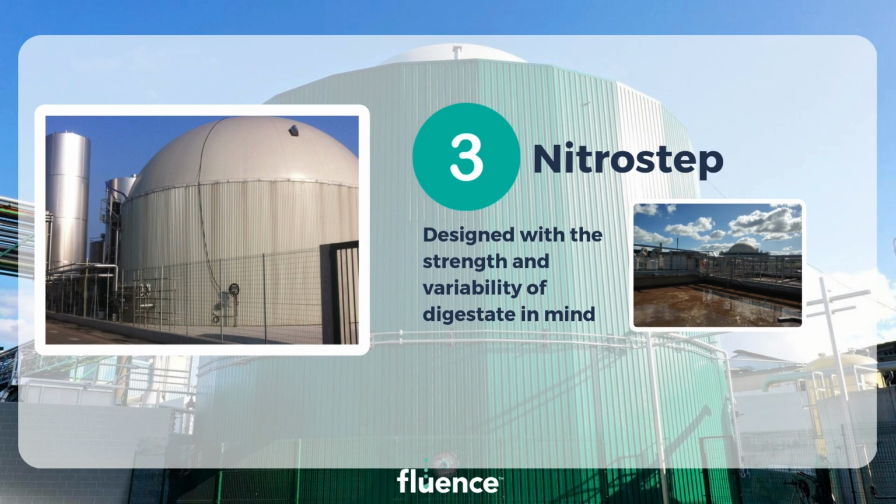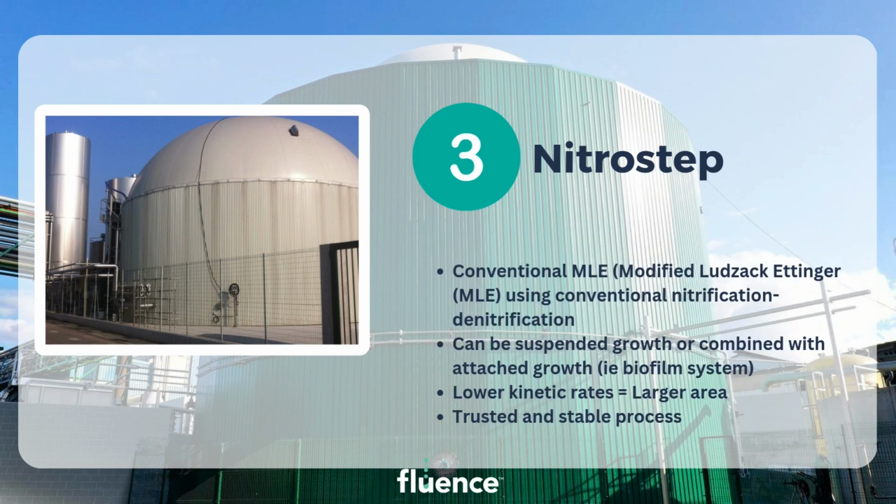The benefit of this pre-anoxic phase is that, number one, we're going to consume a lot of BOD and COD here with very little energy. Number two, the process can actually generate alkalinity, which can help reduce external chemical requirements. And number three, we're further decreasing nitrates, which allows for a much more effective biological solid separation step downstream. As a side note, too much nitrate in clarifiers is a big issue. It can actually degas or off-gas, basically create nitrogen gas if you're not careful in the sludge blanket